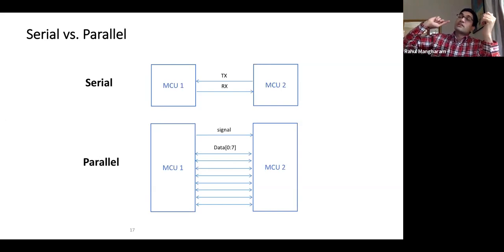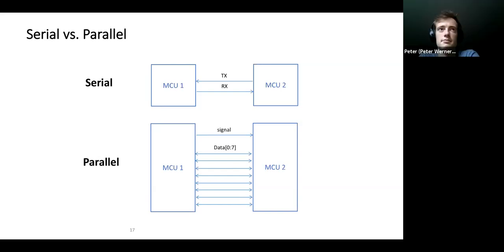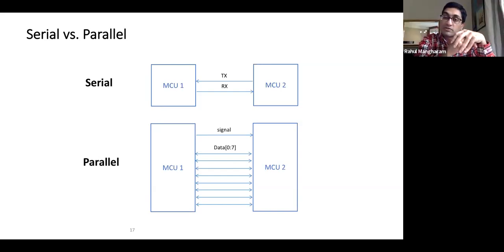you're getting the signal that is bouncing off this wall, that wall, and then coming there. You have signals that are coming directly to you. So the signal is not coming at you at exactly the same time. It's coming at you over some time. And if that time is a little too long, and I send you the next signal before you received all the energy from the first one, then I have inter-signal interference. So yeah, there could be crosstalk because I have many lines. So crosstalk could be one reason.